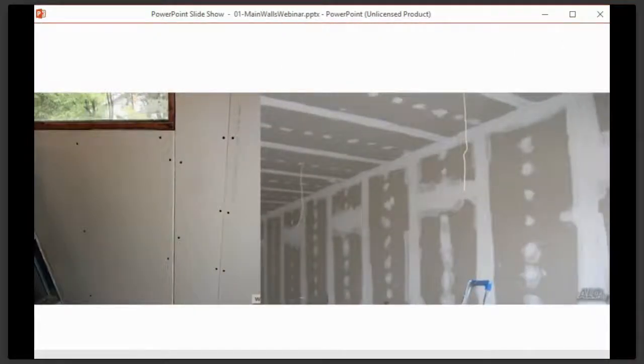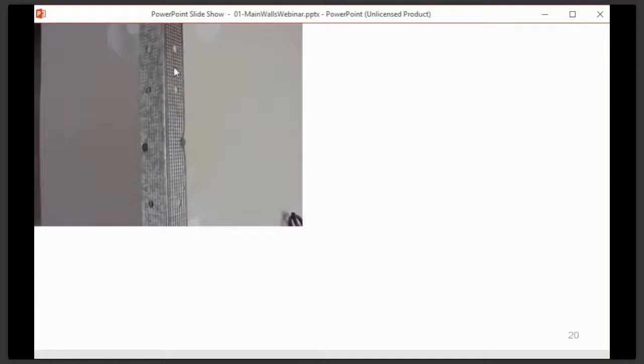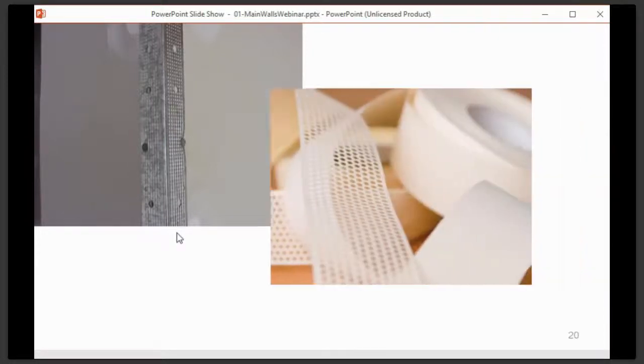So with the plaster, how did they finish it off? Okay, they do this at corners. They put these galvanized steel corner edges, which are screwed or nailed to the edge, and they give a really clear square edge. Because they're metal as well, they give it additional strength. And where the boards butt up against each other at the joints, they cover it with jointing tape, and then they cover it with a jointing compound. So that gives you a smooth finish.